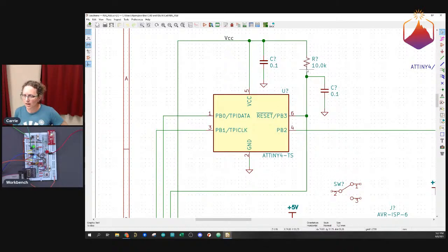The pull-up resistor here is there because reset basically puts your processor into a "dumb, I'm waiting for something" mode. That's how you initiate programming for a processor, and it's how you reset the processor. You do that by attaching this pin to ground. Most reset pins have a little bit of internal circuitry that prevents small blips from accidentally triggering a false reset. And they generally also have internal resistors that hold that pin, we call it pulling that pin high.